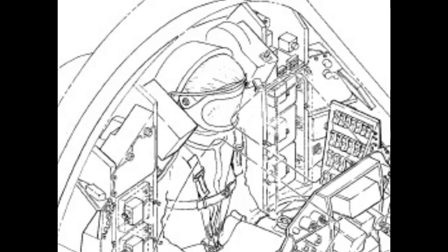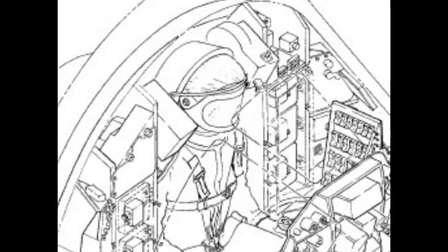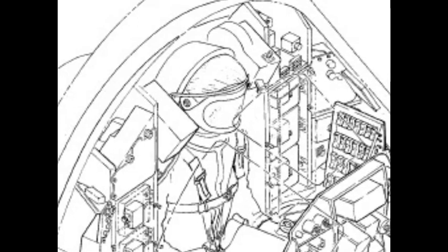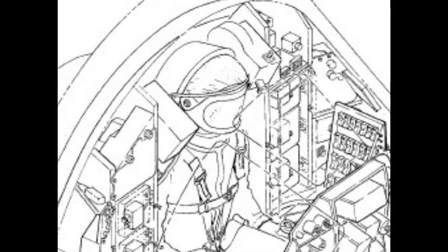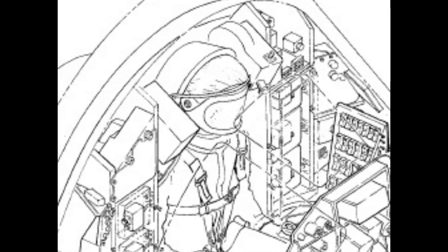215. Missile adapters. 216. Redstone missile adapter. The Redstone missile adapter, figure 2.7, is a shallow, slightly tapered, cylindrical-shaped structure that is designed to mate the capsule with the Redstone missile. The adapter is bolted to the missile and the capsule is attached to the adapter. The adapter is of semi-monocoque construction, utilizing titanium for the primary structure.